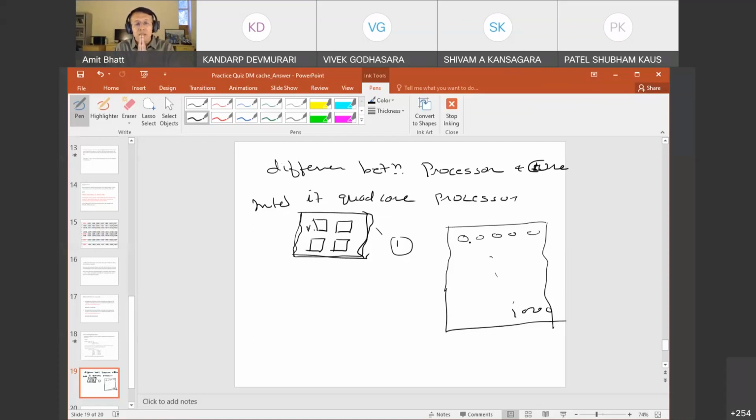So then, you require a processor or a processor core which is very fast. Here each core in the modern processor of Intel is running at 2.5 gigahertz. Now you may ask, why is it not running at 5 gigahertz, or 10 gigahertz? The reason is simple. Frequency is directly proportional to power. So the higher the frequency of a processor, the more power it uses. And the more power it uses, the side effect of power is heat.